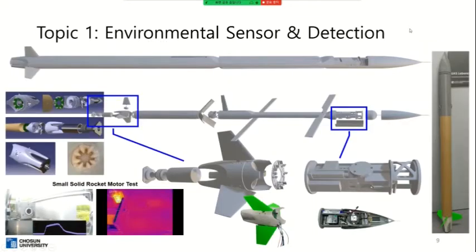In this slide I want to introduce the rocket-based foldable fixed-wing UAV. This is the first prototype, so we haven't tried to launch it until now. We will launch it at the end of this year. We are currently working on the engine parts, and you can see the solid material-based rocket engine. The maximum thrust of this engine is about 100 Newton, and we estimate that it can carry a 2 to 3 kilogram unmanned UAV up to around 150 meters. We already calculated that.